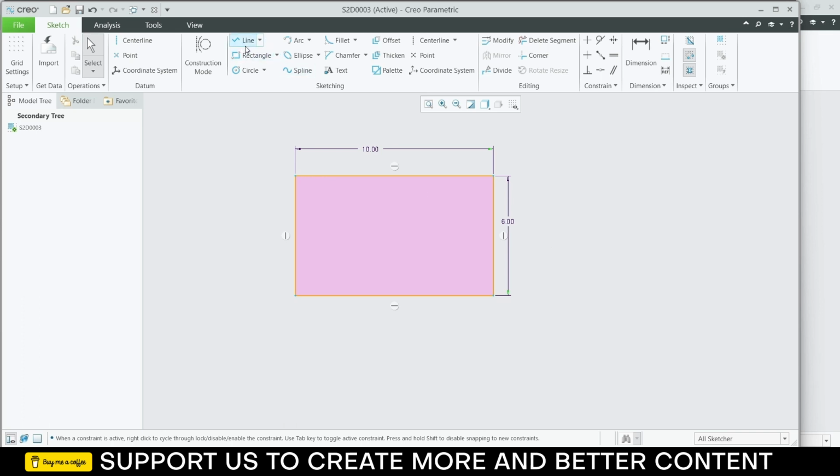Now I will create a triangle again. Click on the middle mouse button to exit this. Now I will click on dimensions by pressing Ctrl and select this point. Click on distance, type 0.5. Do the same from other sides as well. Select this by pressing Ctrl, select this, distance 0.5. Select this by pressing Ctrl, select this, type 0.5. Select this by pressing Ctrl, select this, distance 0.5.